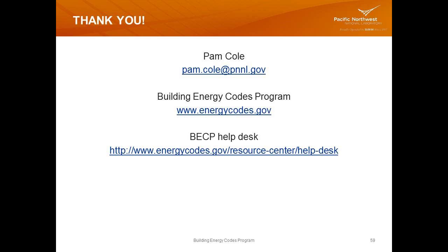The question is, do the requirements not appear in the printed report? Well, the report is separate from the inspection checklist. So you'll want to tie the two together, because all the other applicable code provisions are in the inspection checklist. I recommend you always click on both those buttons. That's why they're defaulted to be clicked on when you get to where it says File, View, Print Report. You'll see the three little buttons and the panel certificate are defaulted to be clicked on. You don't want to forget the inspection checklist. It should go hand in hand, to tell you the truth.